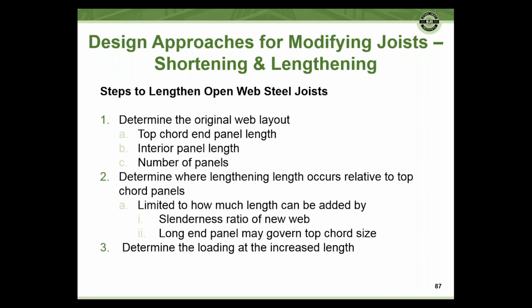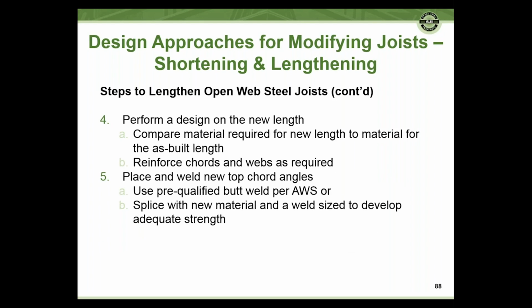So determine the length of that. Remember, when you're lengthening a joist, one of the things we mentioned is that you could get stress reversal in some of the interior webs. When you're lengthening that joist, perform a design for that new length. Find out what the reinforcing member, what forces you have in the existing members. Do any of them need to be reinforced?